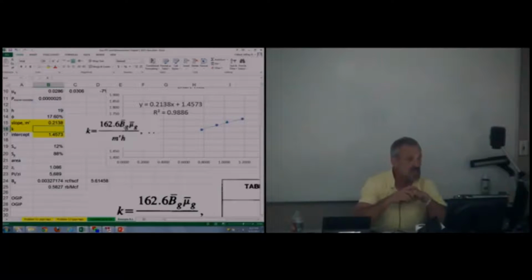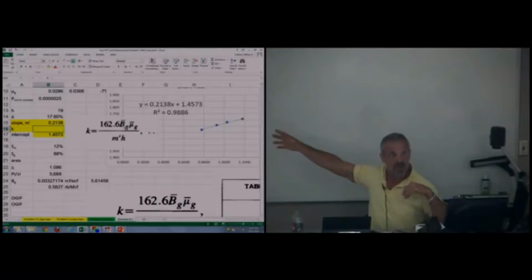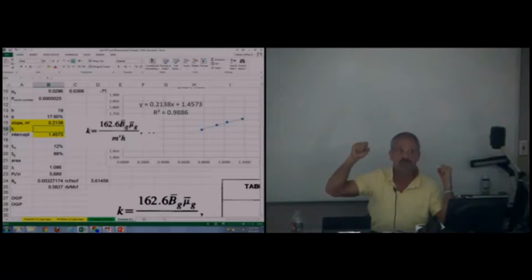But initially, it's initial reservoir pressure. We haven't drawn out in a 6 to 9 hour test enough to even make a tenth of a pound of difference. So we're talking days, weeks, months, years? But on that P over Z plot, if I go down 10 years from now and run this kind of analysis, I don't use initial pressure. I'm using average reservoir pressure. But this is the first test run on a new well. So average reservoir pressure is initial pressure.